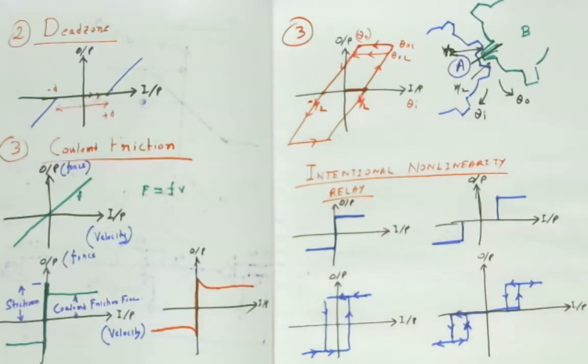There is a thermostat which senses the temperature inside the refrigerator. There is a set temperature. When the temperature of the refrigerator is below the set temperature, the compressor is on, and when the inside temperature is above the set temperature, the compressor is off. The on and off operation is done by the relay.